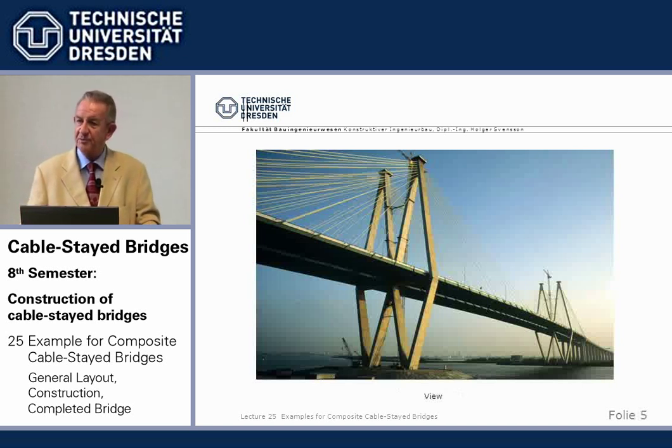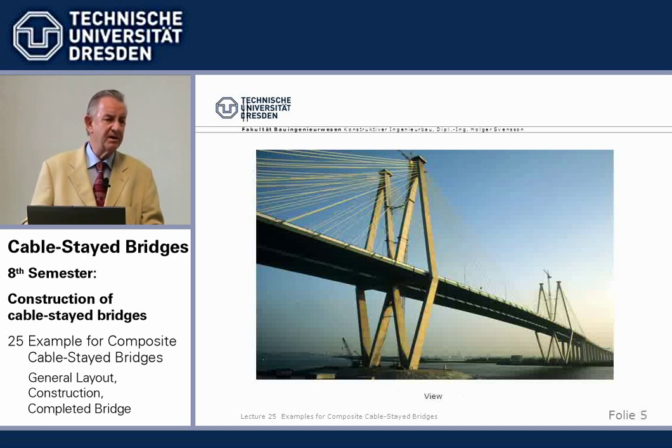Of course, the amount goes somewhere in with the square of the span. And later on it was proven that the 2 independent beams are aerodynamically more stable than any individual beam. So we decided not to connect them, again to save steel, because we were in a hard competition.